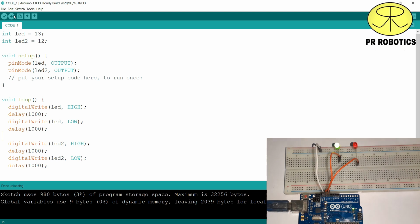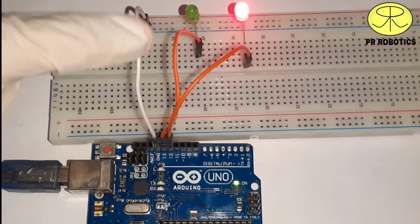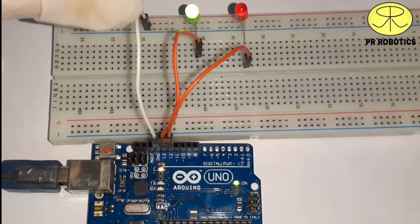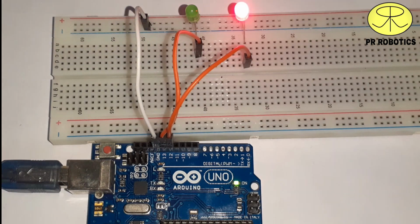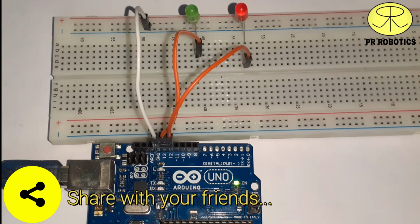So how simple is this? If you were to use the 555 timer IC for this purpose, you would have to build a somewhat complicated circuit, using resistors and transistors. Here we have used just 2 LEDs, but I recommend using 2 resistors of 1K, or you can choose suitable resistors in series with these LEDs, because sometimes they may get burned.